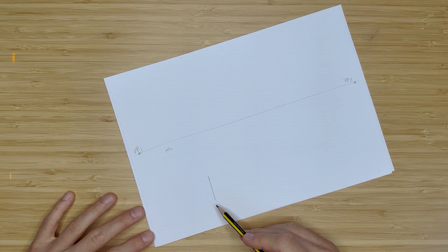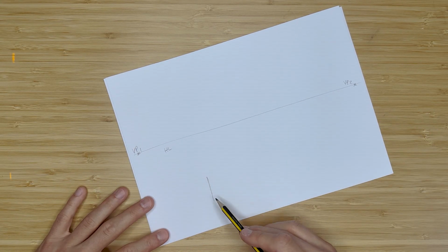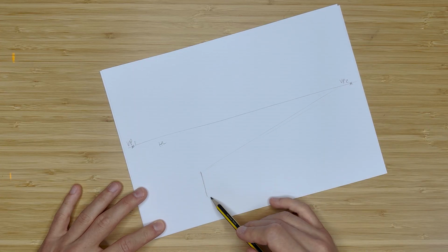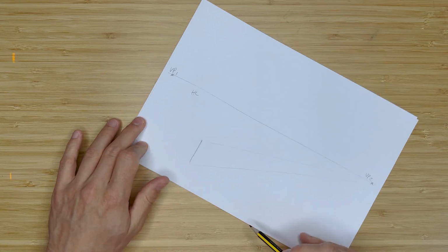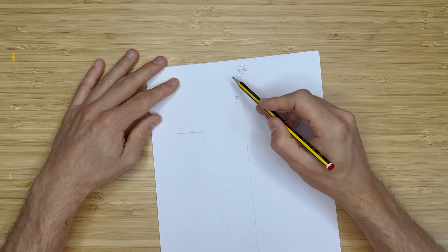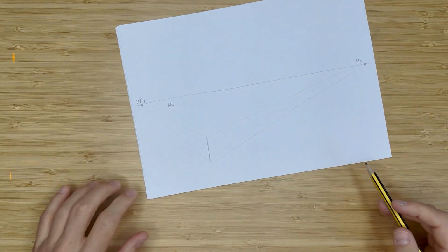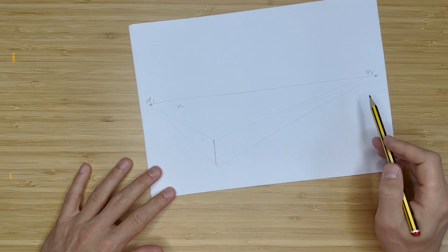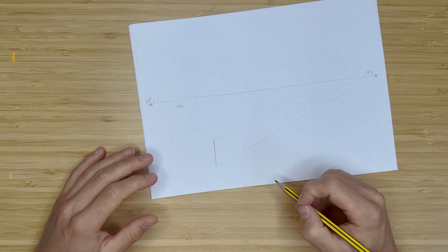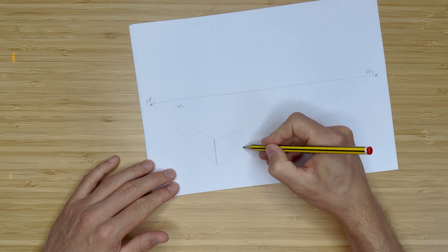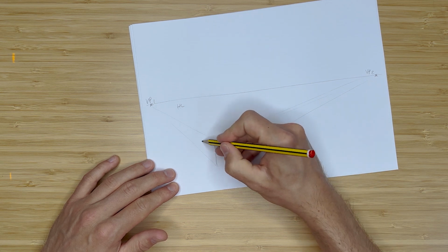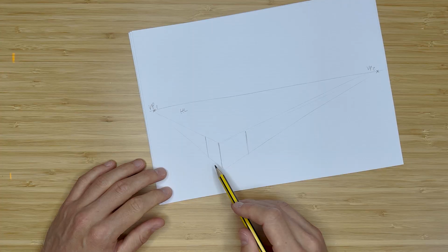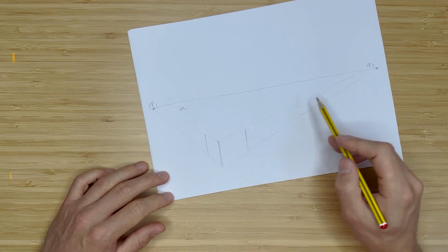And from this upright, we're going to go back from the top and the bottom of the line to that vanishing point over there. Something like so. Nice and light lines. This side, we're going to go back to this vanishing point. So it looks like this. So from 1 point, or 1 line, from the top and the bottom, we've gone back each side. We can now decide the shape of our cuboid. So let's have it slightly longer on this right side and slightly shorter on this left-hand side. And again, from the top and the bottom, they've gone back to the vanishing points because they're on those lines.